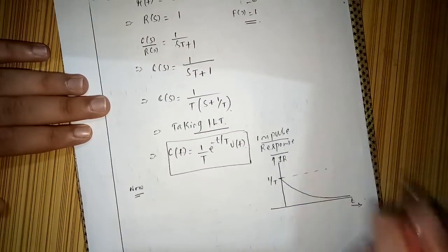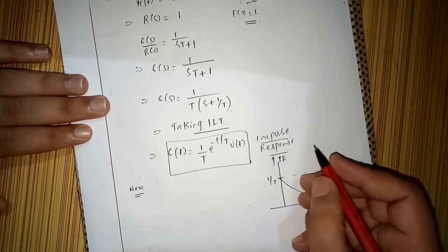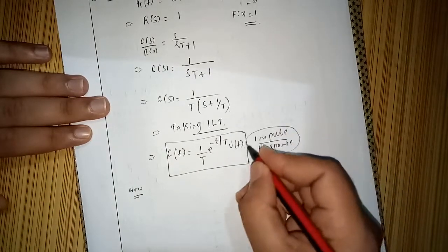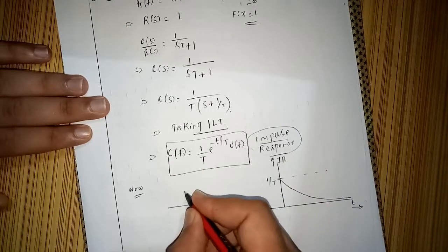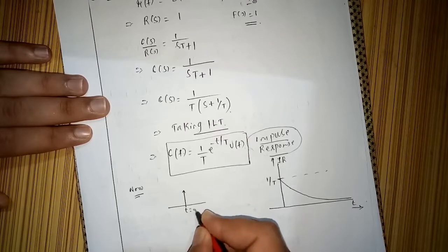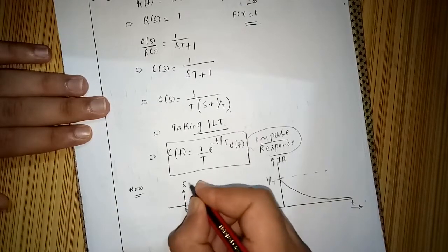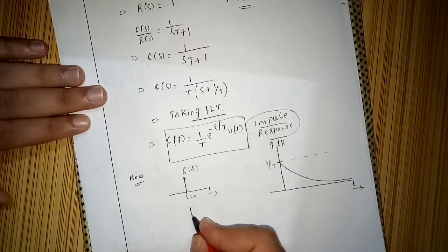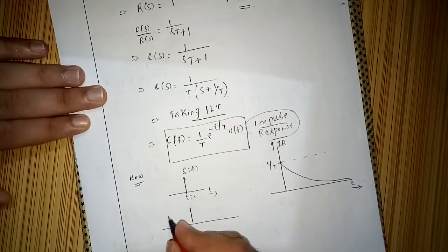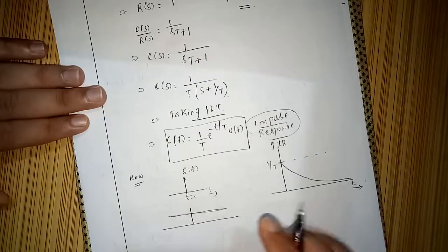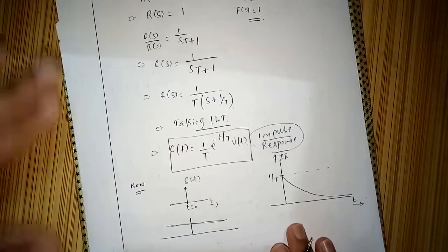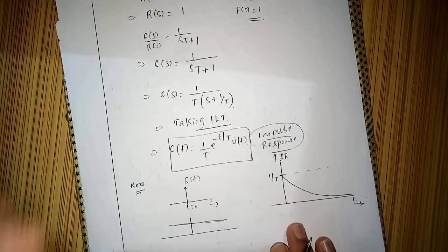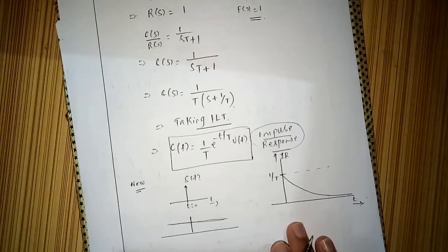And one more thing, why is impulse response so important? Impulse response tells us the response at all frequencies. The input is delta(t) at t equal to 0, but when I take its Fourier transform, it comes out as 1. Fourier transform and Laplace transform are almost the same thing, not exactly the same. You will understand the difference when you cover them in your signals and systems course.